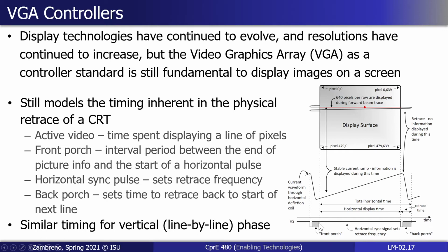And the size of these gaps, both the sync gap as well as the so-called front porch, the time between the start of the horizontal pulse and the actual active video, and the opposite end is called the back porch here. That is what ultimately is going to dictate what the resolution is of our attached display. Given a size of these pulses, there are standard specifications that say here's how many pixels are going to be in that individual row to be displayed for that horizontal active period.